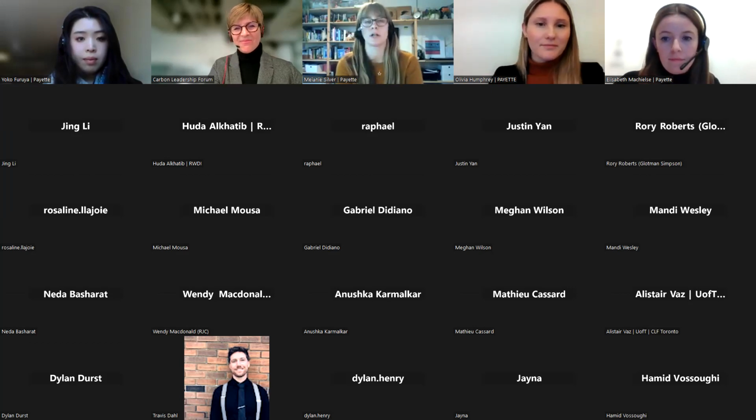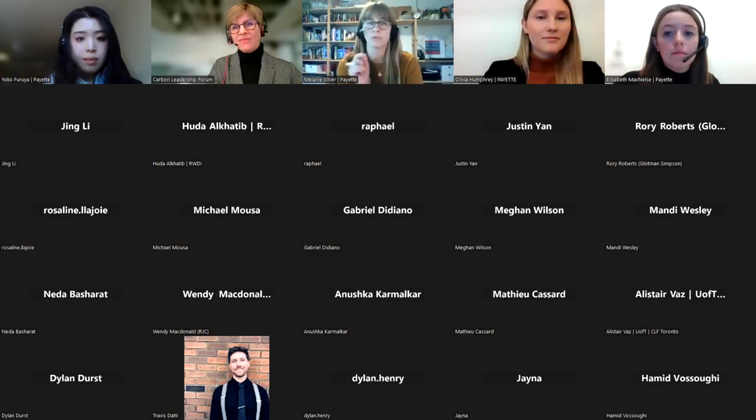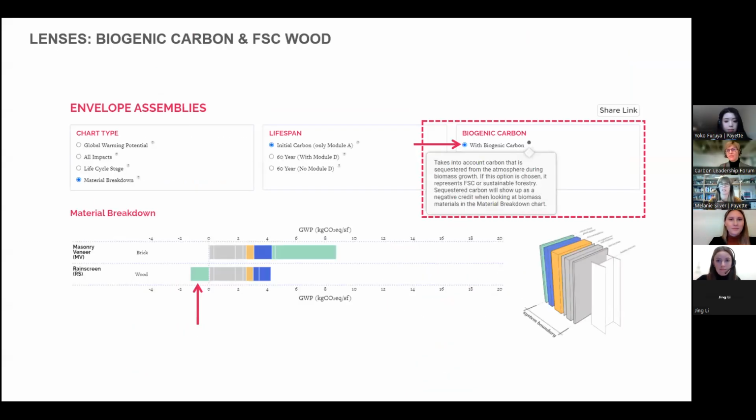Yeah, in the little question mark pop-up, we do recommend that you only use the biogenic carbon lens if you are using FSC or other responsibly forested wood. That's where we're at right now. Otherwise you shouldn't be taking that credit for using biogenic materials. But as Olivia said, there's a lot of research about how to actually account for biogenic carbon, and we've had a lot of these questions. Right now, all we can do is use the data that we have, which was previously vetted through Tally and GaBi and ISO standard, but I feel that might potentially change in the future.